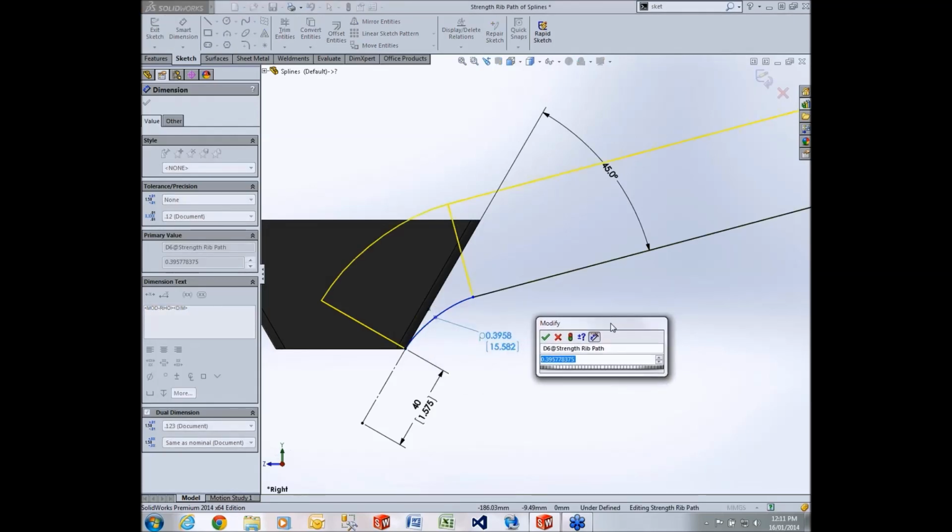The rho value basically sets the sharpness of the conic at the midpoint. So this is a continuously, a curvature continuous shape. So it has zero curvature at these points here where it joins the lines. It will be curvature continuous through, and we use this dimension here, which can change from basically 0.95 all the way down to 0.05. And we can see that it basically moves it almost from a chamfer up to a point, depending on what value you set that rho value to. So I'm going to set the value here to 0.7.